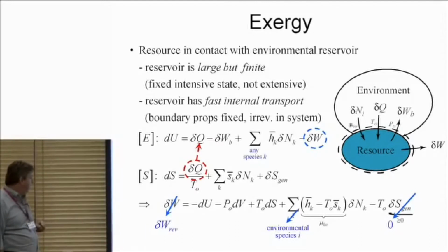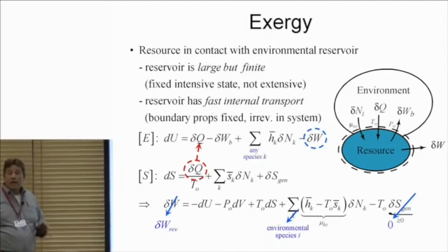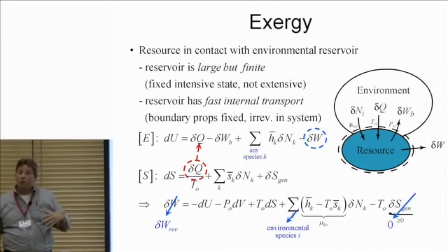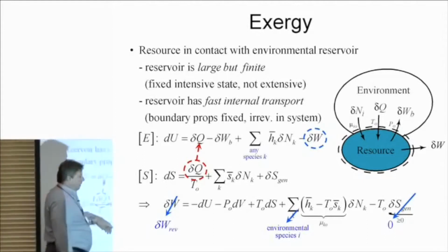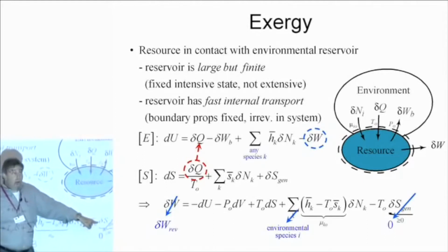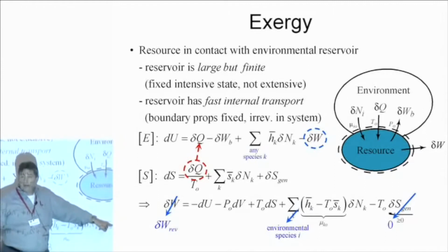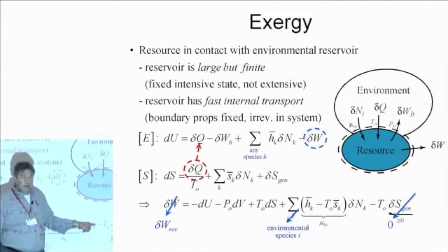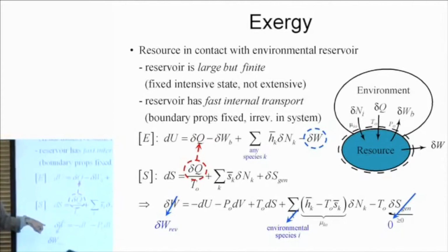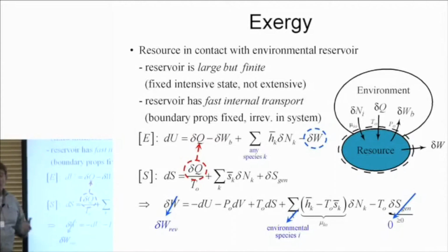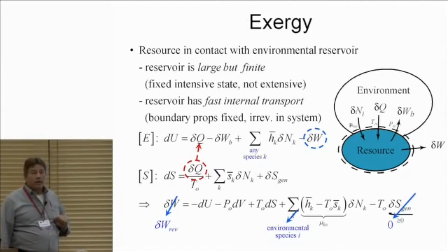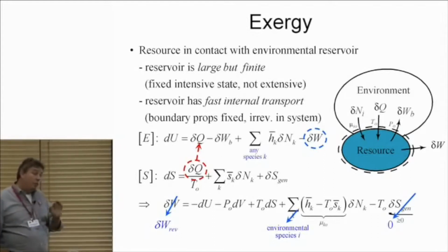Okay, if I take that and I say I want it to be as good as it can be, exergy should be the potential, not what I actually get, but what could I get? What's the best I could ever do? The best I could ever do, this term by the second law has to be 0 or positive. Now in reality, it'll be positive. For anything that actually happens, it'll be positive. That's an intrinsically positive quantity. It's got a minus sign in front. The best I can do is to set that to 0, because otherwise this will always cut into the work I can get. Now what I have is the reversible work for the system, given by what remains on the right-hand side.